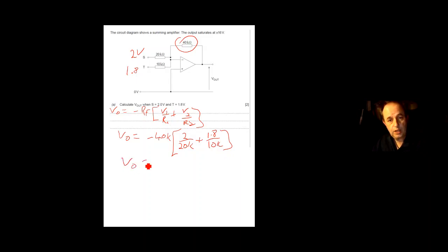That is definitely one you need to practice on your calculator. By using the fraction buttons, what you will get is 11.2, but it's a minus value, volts. That's minus because it's going into the inverting terminal, so it's an inverting amplifier. Summing amplifiers are.